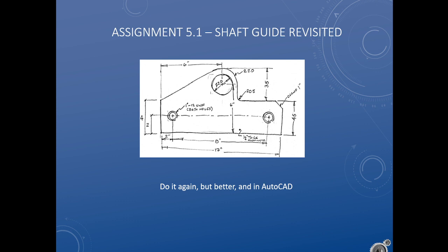Either you make a circle and you trim out a chunk of it, or you make an arc, or you just do hidden lines. That is another standard. Hidden lines are okay. Yes, the outer diameter is the one that matters. So the inner diameter, you can just offset and make sure it's visibly correct. But the outer one is what we dimension to, and you don't dimension it anyway. It's a hole, you make a hole callout, like a threaded hole callout. Yeah, the outer ring is the one that needs to be the absolute right size.